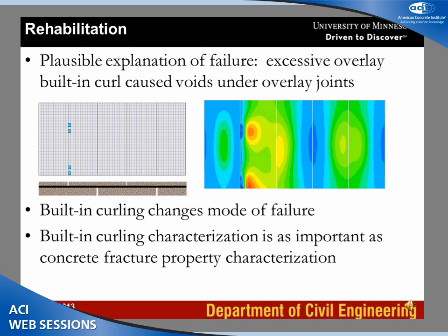On the one hand, after we incorporated a significant built-in curl, now in the overlay only, we managed to predict quite significant stresses on the top of the concrete pavement. But on the other hand, when we placed our load here, I don't have the slide, we still had very significant stresses at the bottom of the overlay, and those stresses were higher than the top stresses in this location.